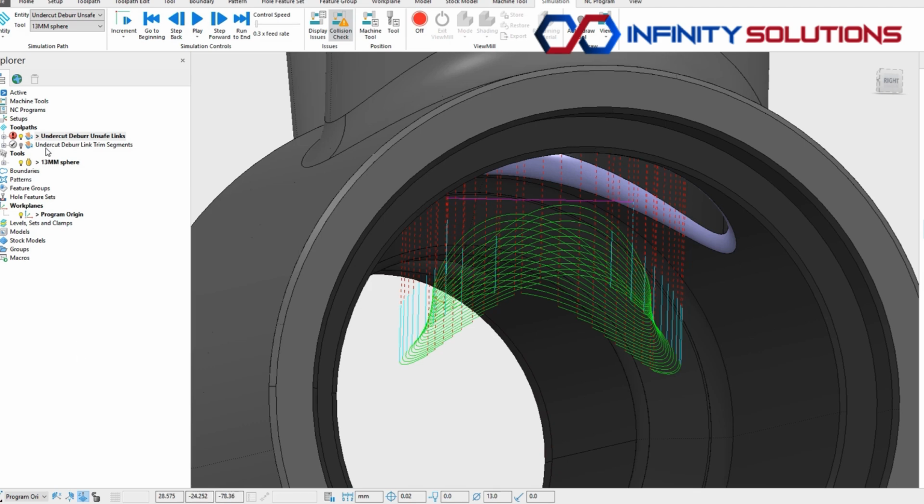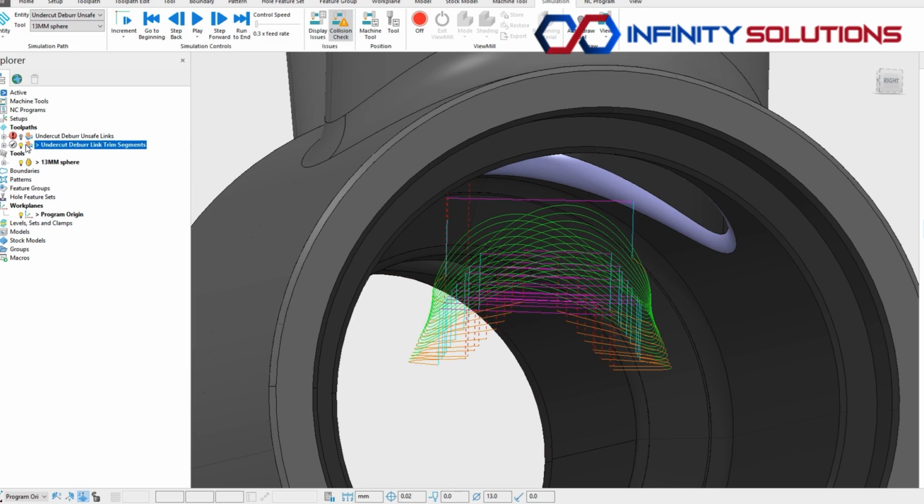When using the Trim Segments option, which has been used for the second toolpath, if the leads and links cannot be applied, then a systematic process is applied, attempting to use other lead options or trimming of the toolpath to try and rectify the issue. In this situation, a lead extension has been automatically applied and trimming has occurred, allowing for the tool to now safely retract.